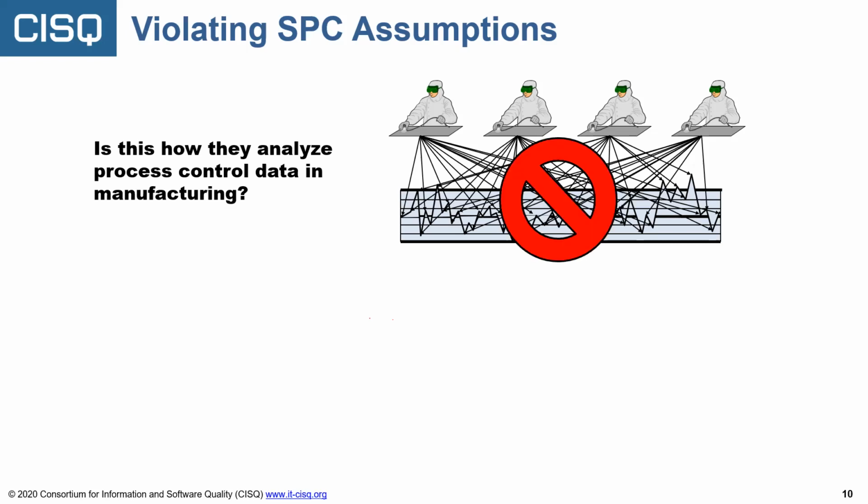Absolutely not, because that throws in so many sources of variation that it just becomes junk, and it'll mask somebody whose machine is going out of control. So each person has their own control chart, and they're mapping their data onto their control chart to make sure their process is staying within the defined 3 Sigma limits, plus and minus, right? So they can see if their work, or their machine, is deviating from the thresholds it's supposed to achieve.